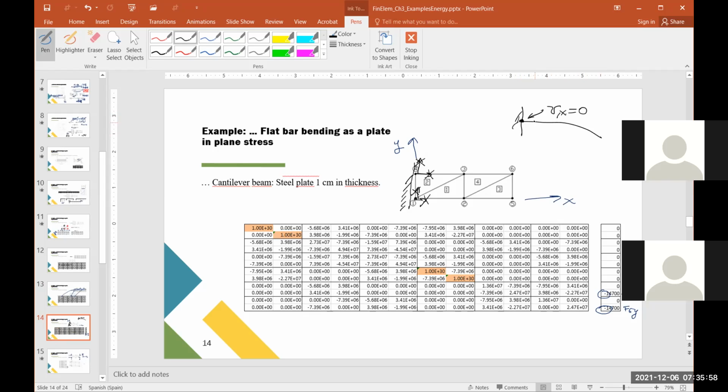But we should do something more. We should put another joint here and consider that this joint cannot move either. In this way, we have two points which do not move in the vertical direction. So we are certain that we're assuring that this is horizontal, and then it starts the deflection. So you see that when we start working with these 2D problems, we get more interesting things to consider. So this is something that we should keep in mind.